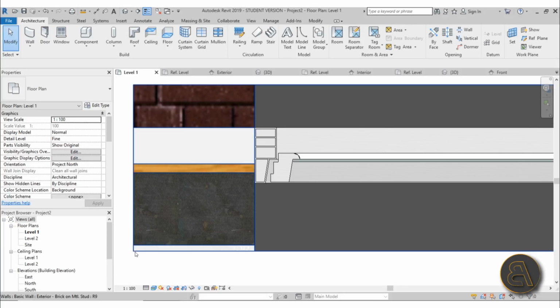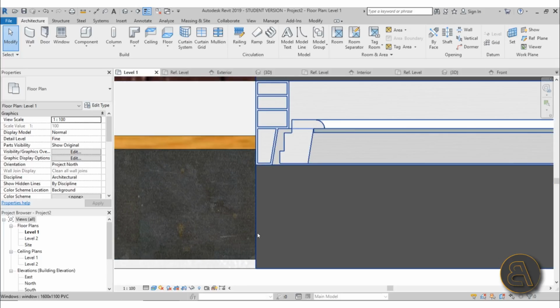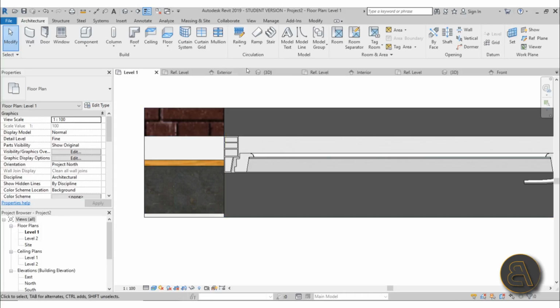Okay, and now just look at the way that these layers are being finished. We have some inside finish layer over here, maybe some gypsum wallboard or something like that, and it's just finishing over here. Usually it doesn't work like that in real life. Usually layers need to fold around your window when you're finishing it off like this. Usually you don't have concrete exposed at your windows. So let's see what this change will make.